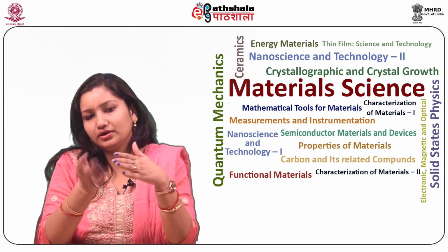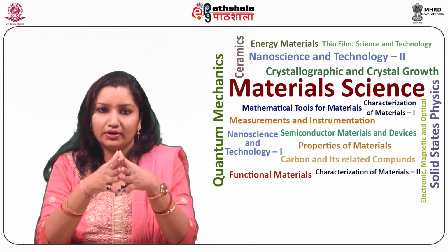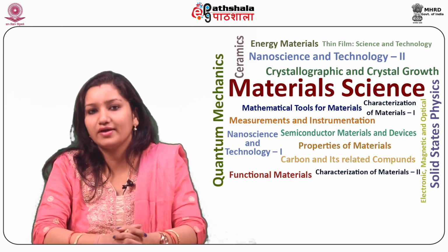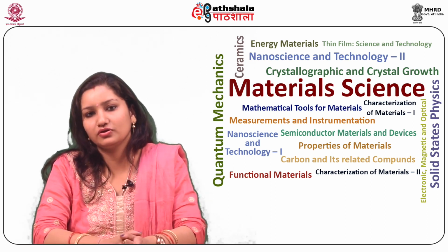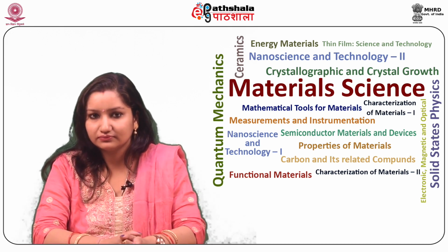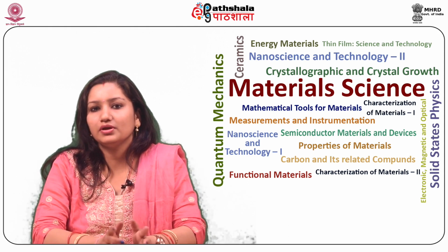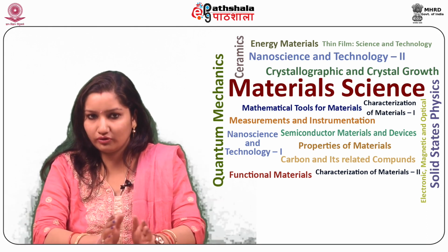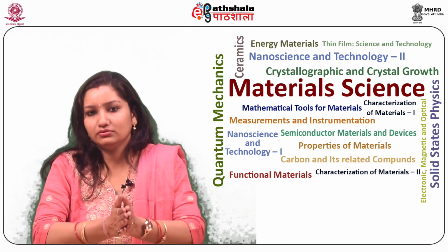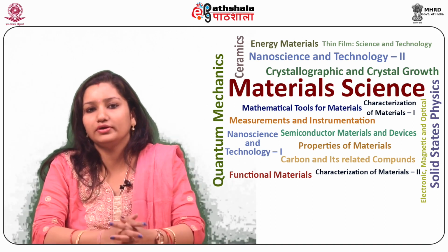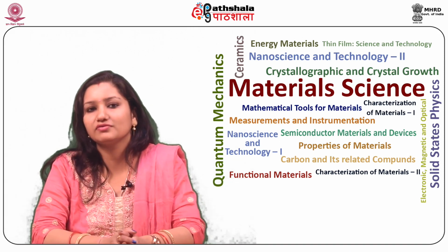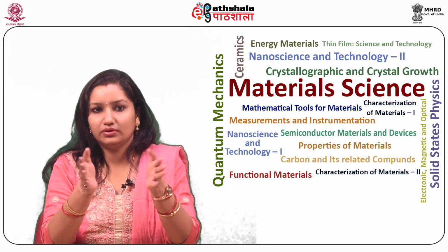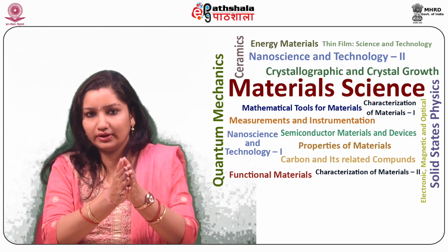Direct conversion of light into electrical energy is called photovoltaics, denoted by the short form PV. Photovoltaic devices which convert solar energy into electricity are called solar cells. Two electronically dissimilar materials with different free electron densities are brought together to form a junction with a barrier, forming a photovoltaic device. Typical examples are metal 1, oxide and metal 2. This forms a junction and it will be a photovoltaic cell.